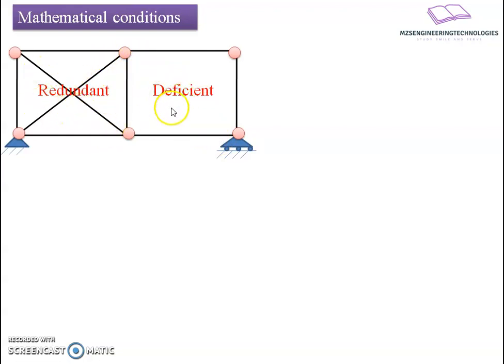This situation arises in general design when there are constraints for a designer to put in such a geometry. For example, if it is a foot over bridge and there is a passage here made for the movement of pedestrians, then it's not possible for us to provide a cross bracing here. In that case, I have to balance the geometry, so I will remove the cross bracings here.